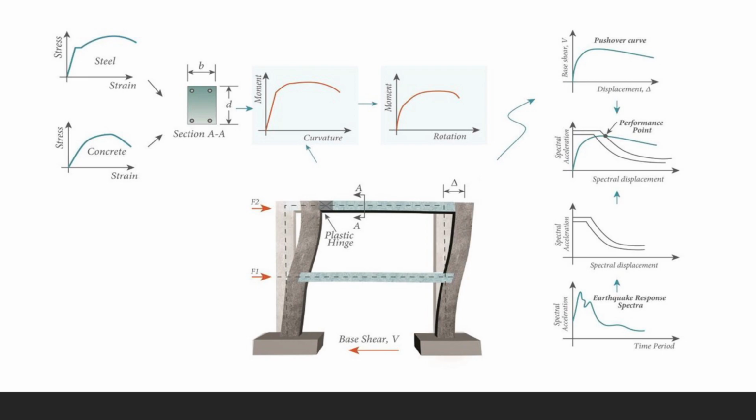So that is the point where the earthquake and the structure's performance meet, and then we can see whether it is life safety, whether it is immediate occupancy or not, because these displacements are actually defined on the structure's performance curves, or the members' curves. So that's how we can connect the design decisions with the earthquake, with the expected performance. And this whole process requires advanced modeling, advanced analysis. It cannot be done by traditional methods because it requires nonlinear modeling.